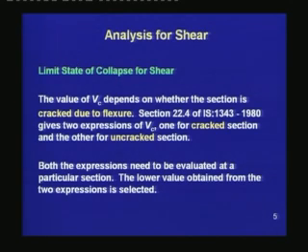Last time we had studied that when the concrete member is loaded, first the flexural cracks are initiated, next the flexural cracks tend to become flexure shear cracks as we move out from the midspan, and then we may find some web shear cracks developing near the supports. The shear strength of concrete depends whether the section has cracked or not.